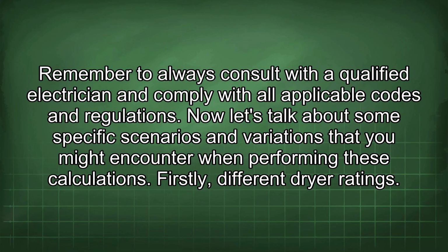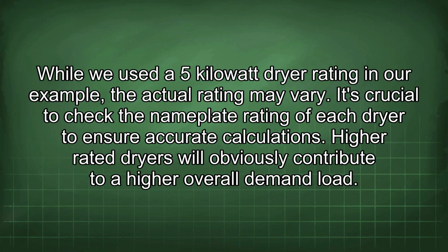Now let's talk about some specific scenarios and variations that you might encounter when performing these calculations. Firstly, different dryer ratings. While we used a 5 kilowatt dryer rating in our example, the actual rating may vary. It's crucial to check the nameplate rating of each dryer to ensure accurate calculations. Higher rated dryers will obviously contribute to a higher overall demand load.